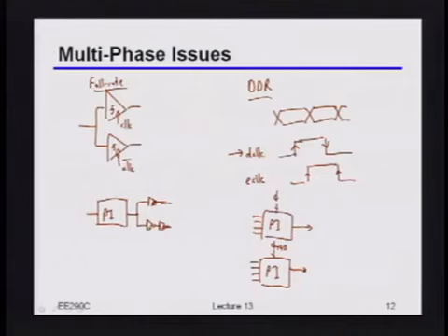Mismatch. Yeah, mismatch, right? So the obvious one is that just first of all, even if they were all the same phase interpolators I had before, they're going to just burn more power, right? Just linearly with the number of phase interpolators. Now, that's not exactly true because the frequencies maybe aren't fixed, but roughly speaking, power and area goes up, right?